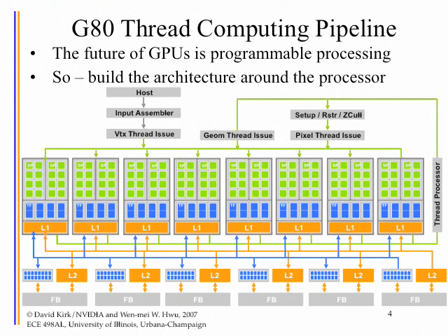So what happens is that, when they produce the G80 GPU, they actually produce a piece of hardware with 128 of these execution units called streaming processors. And we're going to actually go into a little bit more detail so that you can really understand the performance characteristics of these things. 128 of those essentially are used as a pool of execution units that can handle rastering and rendering and all that stuff. Okay, so when the graphics execution commands come in,